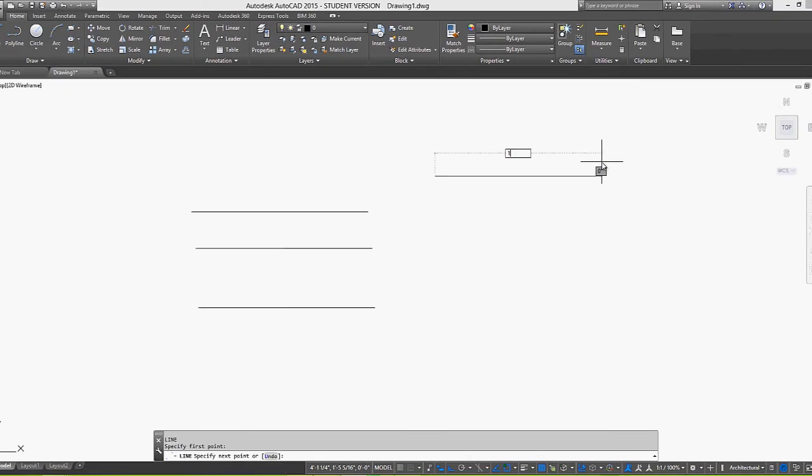Okay, so I'm going to type in 1 foot. Okay, we always have to have that foot tick. But then I want a 1/2 of an inch. Okay, I don't want a 1/2 of a foot, I want a 1/2 of an inch. So I'm going to type in, okay, dash 1/2 inches. Okay, again, that dash is optional, and again, that inch tick is optional. So I'm going to hit enter and then enter again.